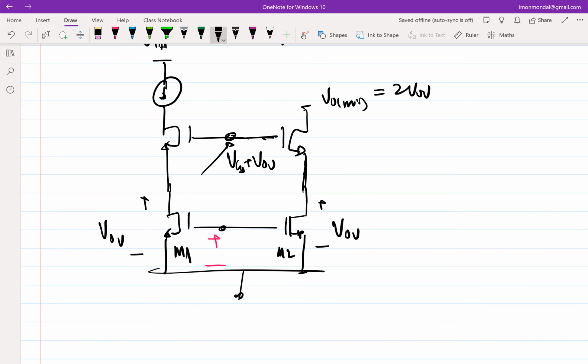We argued that it's a negative feedback. We are observing the drain voltage. If the drain increases, it's giving me information: that I have to increase the strength of the transistor, I have to increase the gate voltage to accept that current. So I connected drain to gate. You recall, like ages back when we were initially doing negative feedback. Now today is the last class. Now tell me, how do I proceed with the same argument?